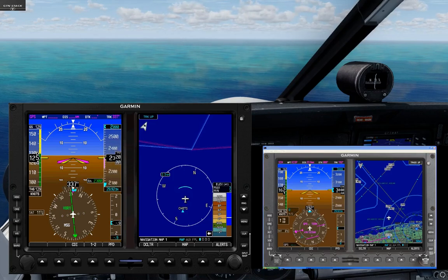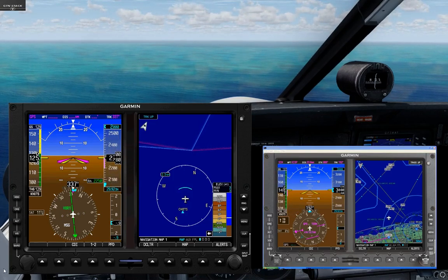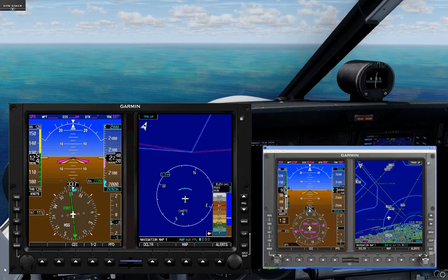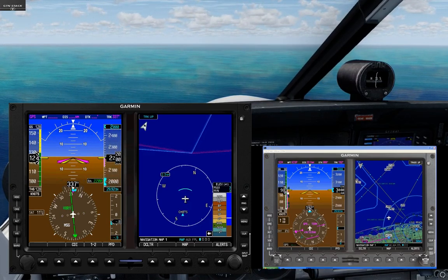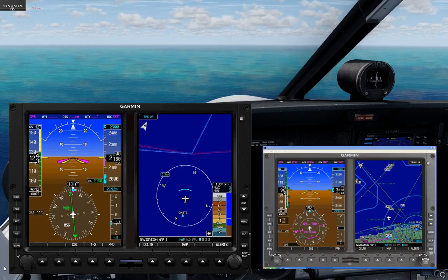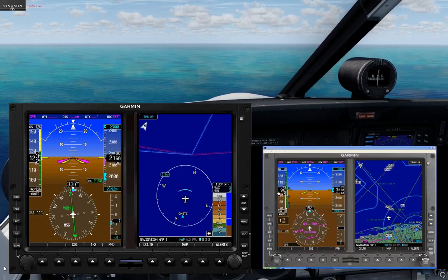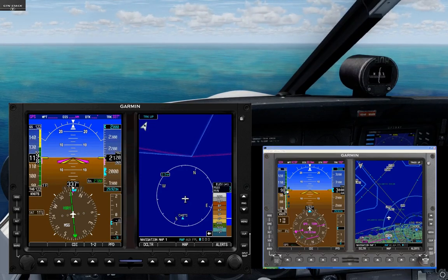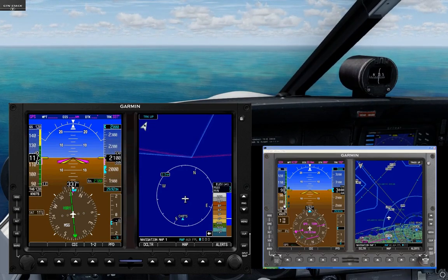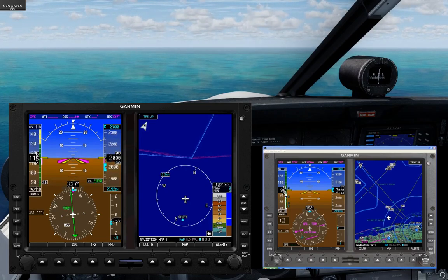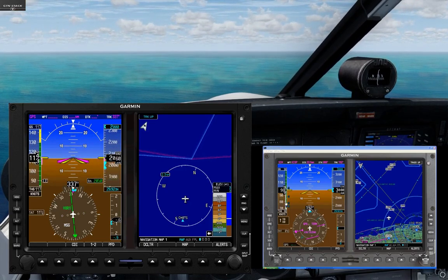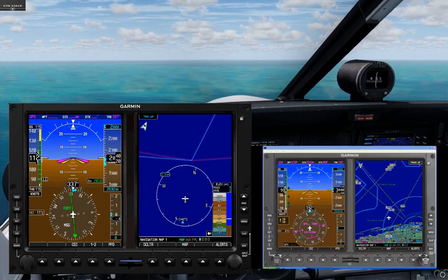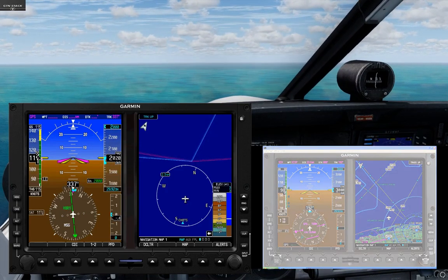I'll reduce that airspeed one more time just so you see that trend vector appear for the airspeed. We see any bugged airspeeds here, in this case VY, just above our current airspeed, trend vector disappearing. You can see here we're in the white arc now, flap operating range for that particular aircraft model, and that's basically climbs and descents.